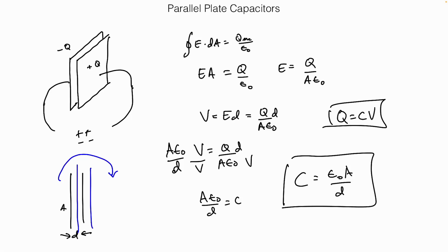If you've got a nice flat piece of plastic or cardboard or anything else that's an insulator between those two conducting plates, you make the conductors as thin as possible. Let's see, maybe mylar film. And then you roll that whole structure up. It can turn out looking like a cylinder, but in fact, still be a parallel plate.